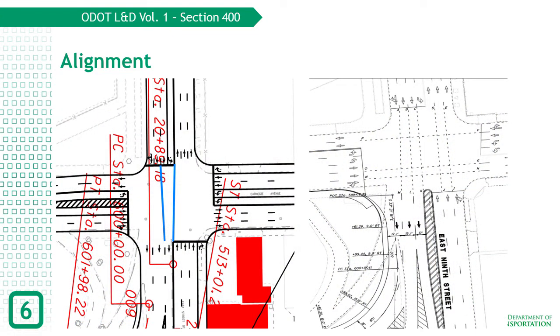Let's look at an example of a horizontal deflection through an intersection. The image on the left was a first proposed design in downtown Cleveland at East 9th Street and Carnegie Avenue. Notice the deflection of the two inside through movements showed in blue. The southbound inside through movement must shift east almost an entire lane width, which could easily create path overlap problems with the adjacent through lane in the event they both attempt to enter the middle through lane south of the intersection. The northbound through lane must shift nearly half a lane to the east. This could create a potential conflict with the opposing left-turning traffic.